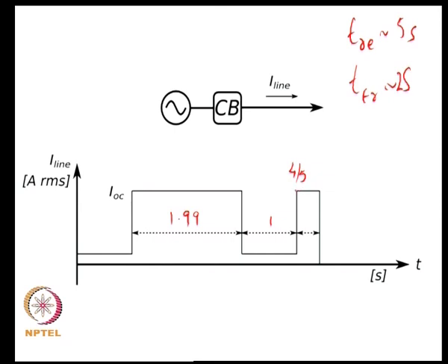So, the question is now, if your overcurrent again came up to the same value of IOC, it will not need another 2 seconds to trip, but it will need a smaller amount of time to trip. It would have typically required 2 seconds, but you have only 1/5 of the distance for the tripping action to occur. So, it would need about 0.4 seconds for it to trip.